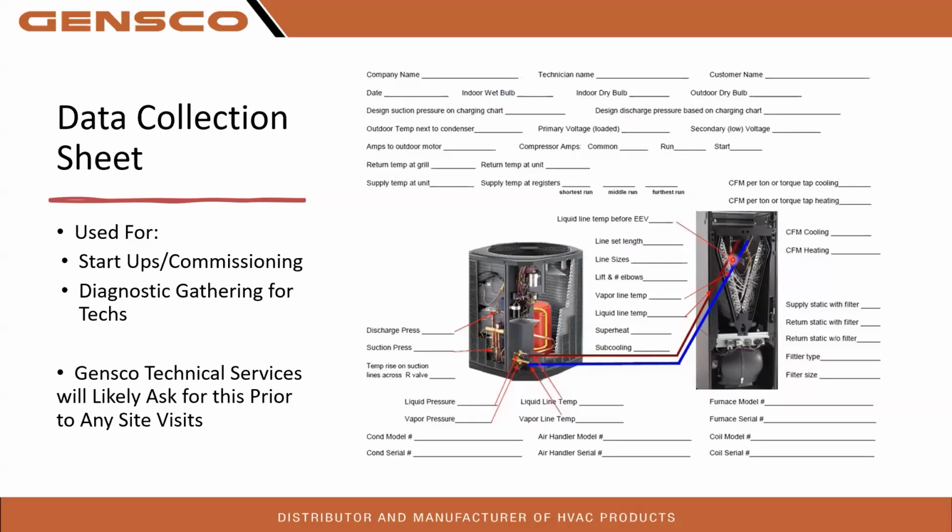All this information, as frustrating as it could be to have, allows us to help and assist you guys. So something as simple as filling out this sheet, and then I look at it and go, wow, our airflow is great. Our static pressure is great. We are moving the right airflow. We have the right filter. What's our suction pressure? What's our liquid pressure?